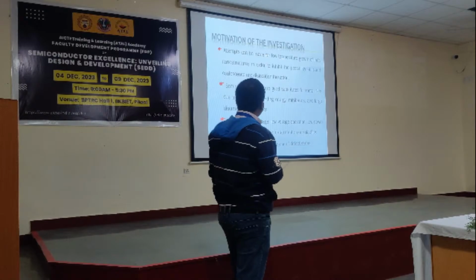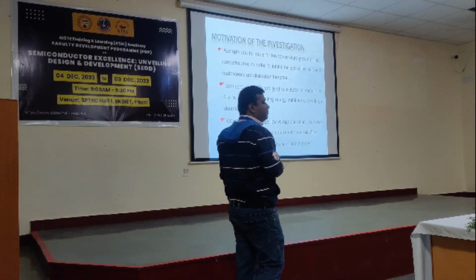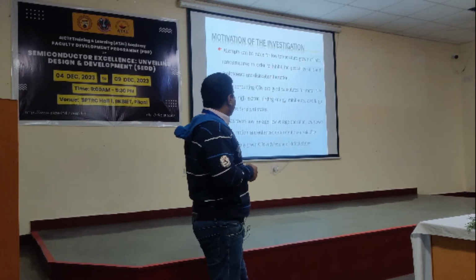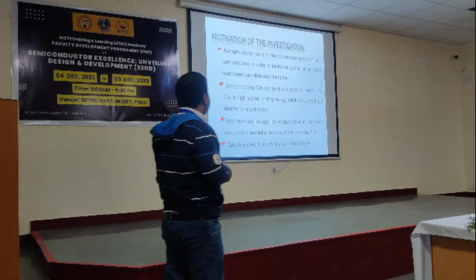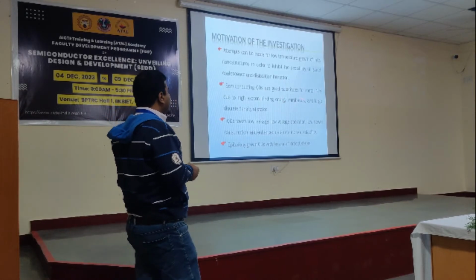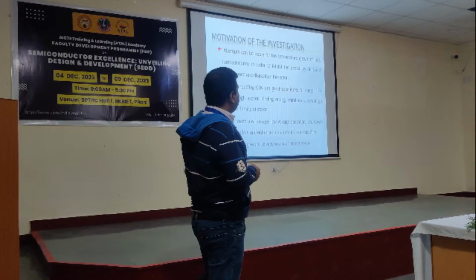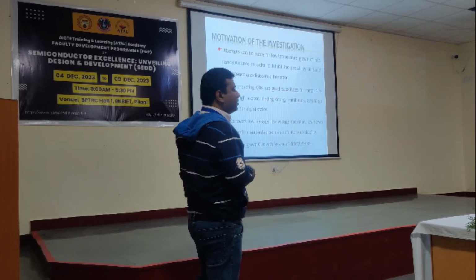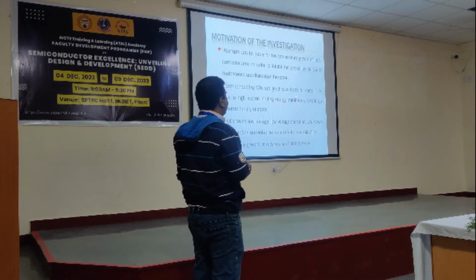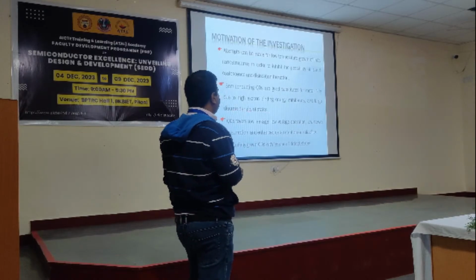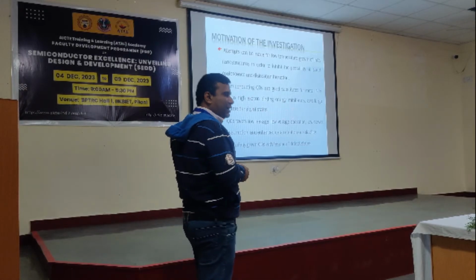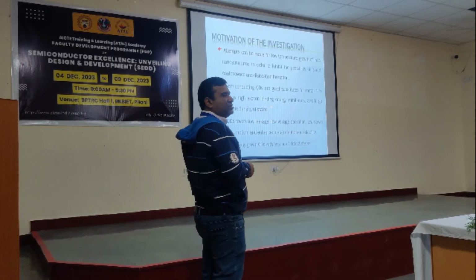Now, the motivation: I told you, in previous literature many reports are available where in most cases the growth has taken place at 500 degree C to 600 degree C. People are also using nanoparticles, but instead of nanoparticles, I have used semiconductor quantum dots, that is, indium arsenide quantum dots as the charge storing element. Why? It exhibits many advantages: high exciton binding energy, formation of many bands with a large discrete density of states. Because whenever you go from bulk to nano, many discrete energy levels are created that are responsible for storing your charges, right?